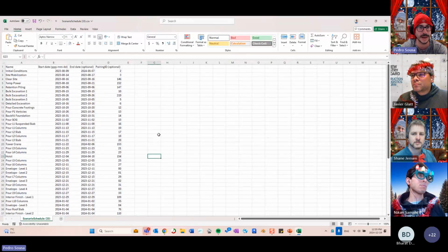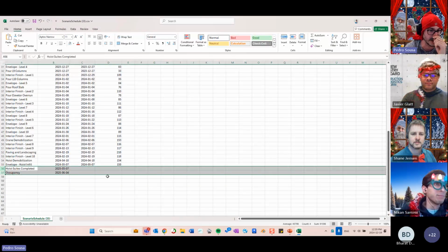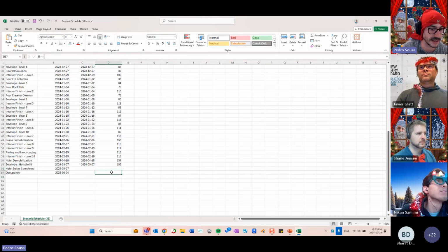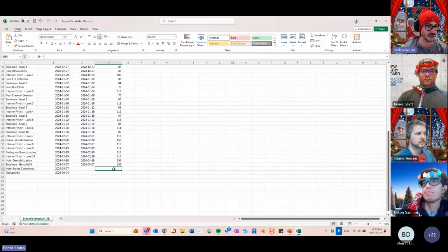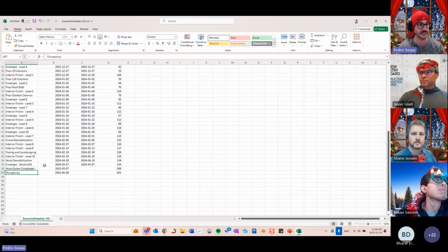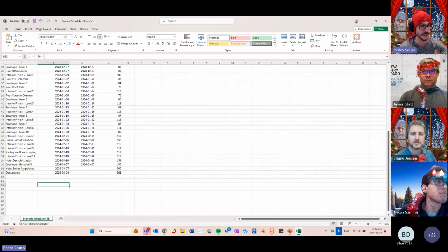One thing that might block this process is that whenever you have manually created milestones like these two over here, you're going to have blank values in your pairing ID, and the software doesn't understand that those are unlinked milestones. So you need to put some fake IDs over here so the software understands that they are supposed to be brought in, but they are not going to link to the manual milestones that are over there. What's going to happen is that we're going to create a duplicate of these two. So you're going to have another host suites completed, another occupancy going on over here.